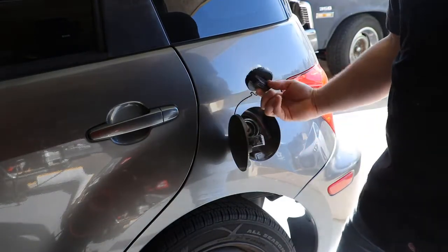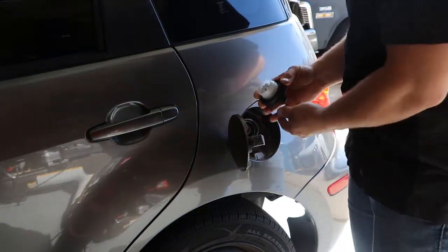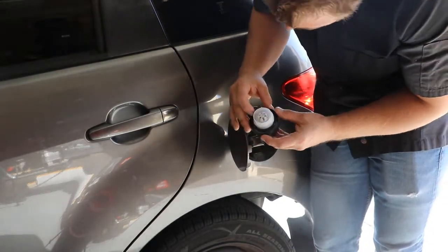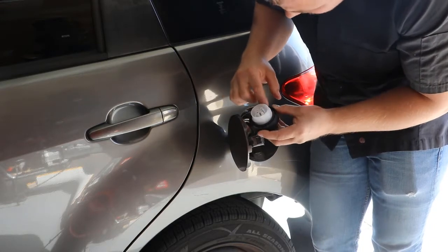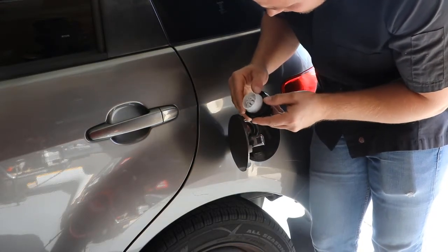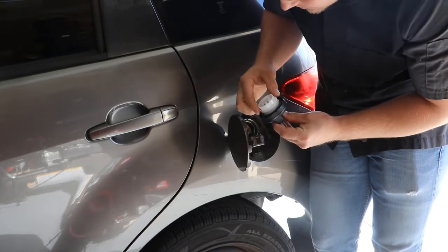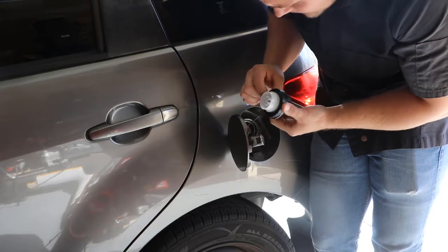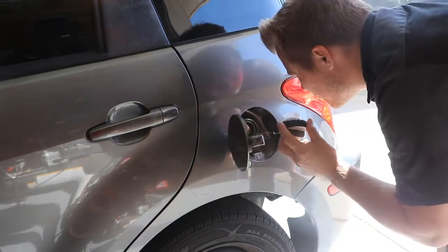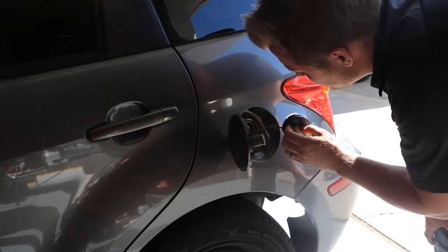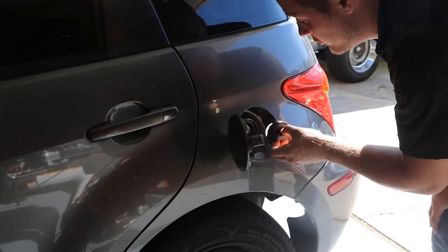So we're going to open it and take it off. First of all, as you're taking it off, notice whether it was on tight. This gas cap was not on that tight, so that could have been a problem as well. But after checking it, it is a new gas cap. I'm checking the rubber seal around it. The seal looks great, and this cap is for sure brand new. The spring looks to be in good condition. You can usually get a tool that can check the pressure on these, but it looks to be in new order. Check the round of the receptacle as well, making sure there's no scarring or damage to the gas receptacle itself, to make sure it's not leaking gases or vacuum through the sides.